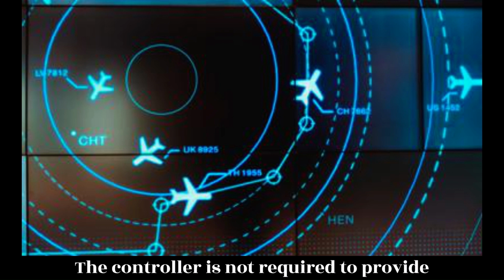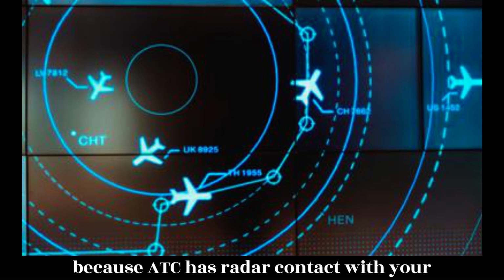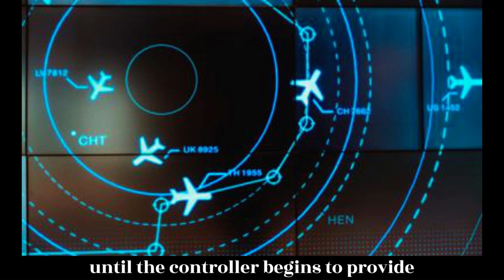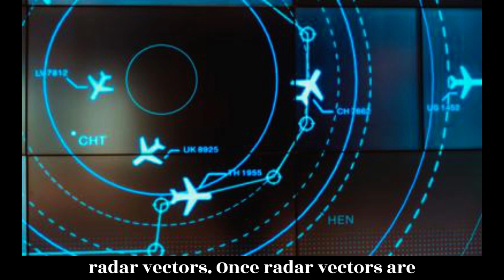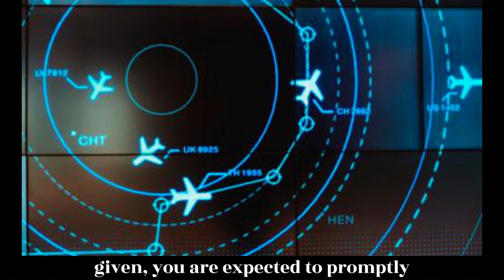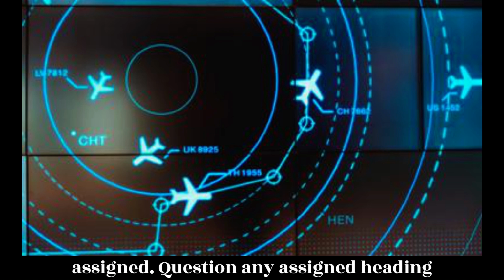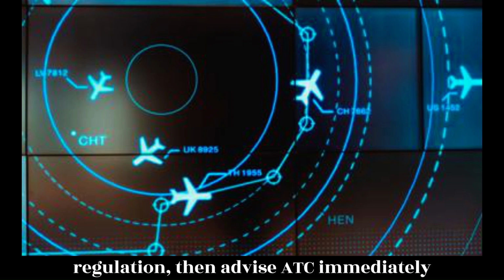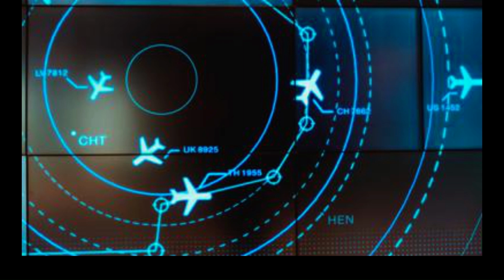The controller is not required to provide terrain and obstacle clearance just because ATC has radar contact with your aircraft. It remains your responsibility until the controller begins to provide navigational guidance in the form of radar vectors. Once radar vectors are given, you are expected to promptly comply with headings and altitudes as assigned. Question any assigned heading if you believe it to be incorrect or if it would cause a violation of a regulation, then advise ATC immediately and obtain a revised clearance. End of page 1-38.